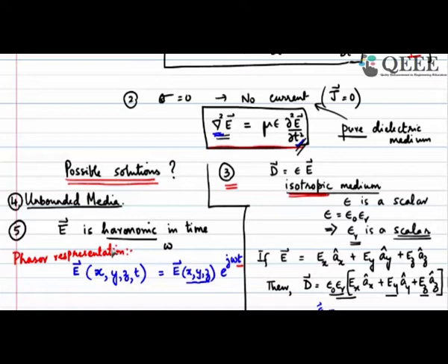When we wanted to calculate the impedance of an inductor or capacitor, when analyzing an AC circuit which has an inductance and capacitance, it was easier to use the time harmonic case because we could use a phasor representation. The power of phasor is that the moment I put it as a phasor, all the second derivative will vanish. Second derivative in time, I can write it as a multiplier. I don't have to do a derivative. I'll show you how. But that was the power. We have used it in electric circuits. Same thing we are going to use here.